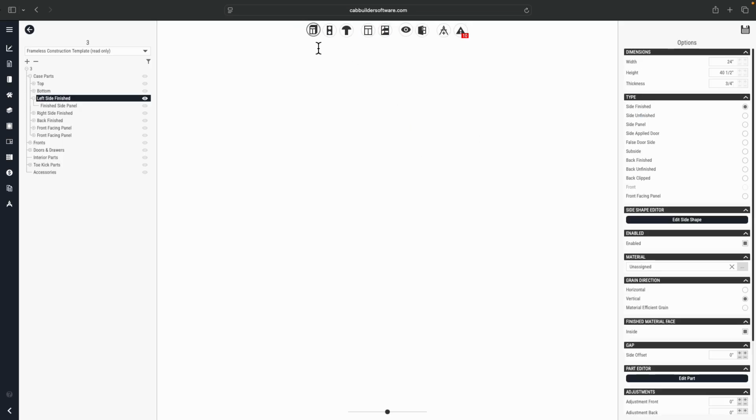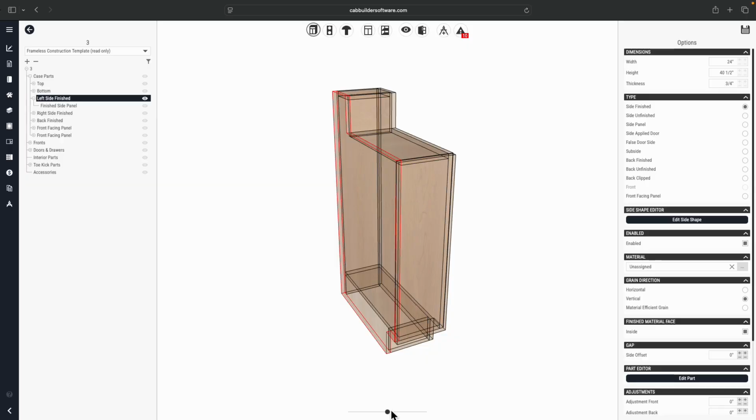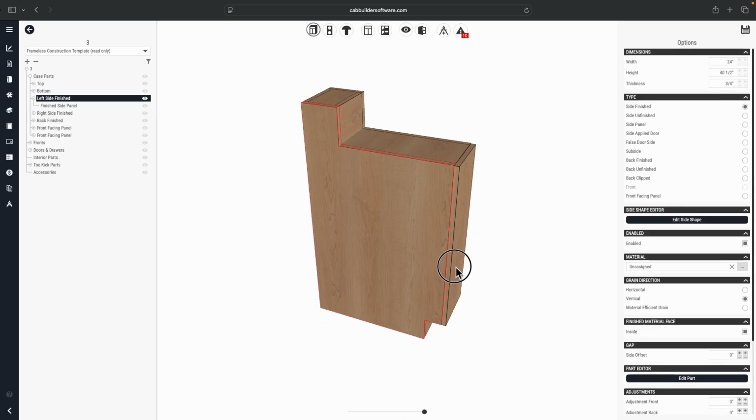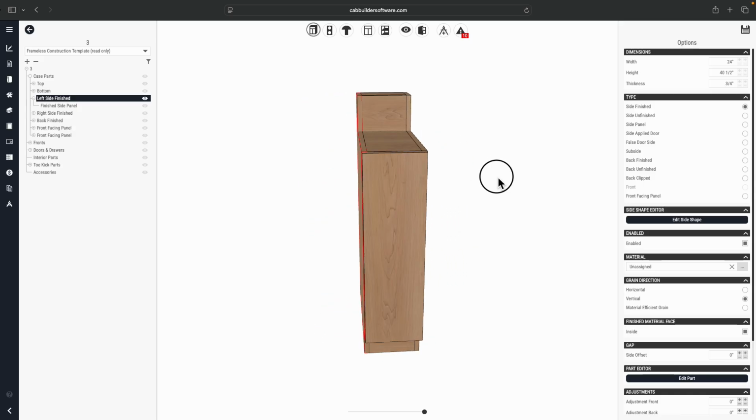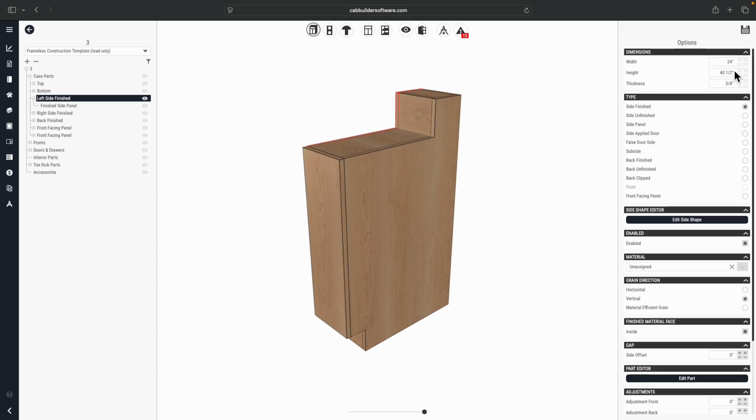And if we look at the result within the wireframe editor, I have what I was looking for. So again, a top bar countertop, and then we'll have this be the other piece. Once I hit save, the cabinet profile will be locked in. Now this utility allows for a wide range of non-standard cabinets to be made, including ADA sink cabinets.